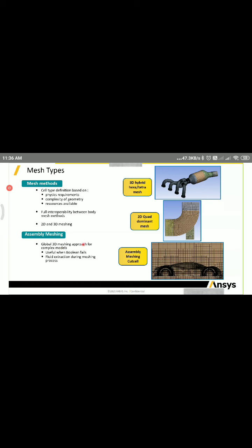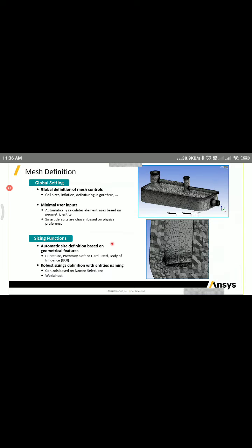Okay. You have the pixel algorithms also available within this meshing tool. So if you want to use it, you can use it here. But as I discussed, it's always good that you use the fluent meshing for CFD requirements and for catering to the different composite geometry. And you have different meshing definitions in the workbench, like you can give the global size, what is the minimum size you want to start with, what is the max size you want to reach, what is the curvature you want to capture, the curvature size, right?